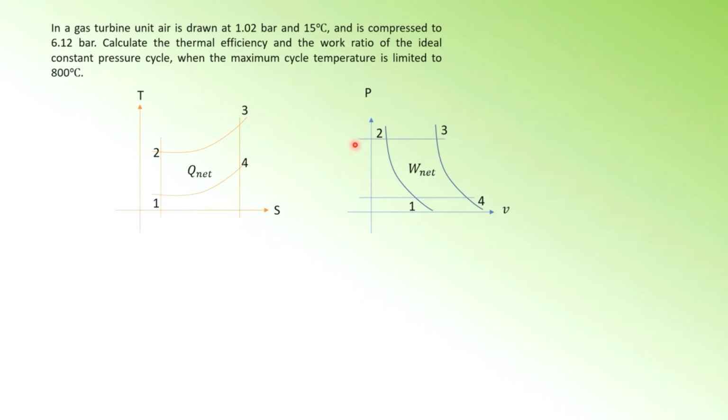So on the PV diagram, remember, again I repeat, 2 constant pressure and 2 isentropic. You can see the curve on the PV diagram for the entropy, the slope is usually greater than when you draw a temperature curve on the PV diagram. So the entropy curve usually is greater in slope. That means it's steeper as compared to the temperature curve on a PV diagram. On the PV diagram you have pressure and volume already, so the only 2 things you have to know are the entropy and the temperature lines and how they look on the PV diagram, which I've shown you on the previous slides. Okay, so these 2 are your constant entropy lines.